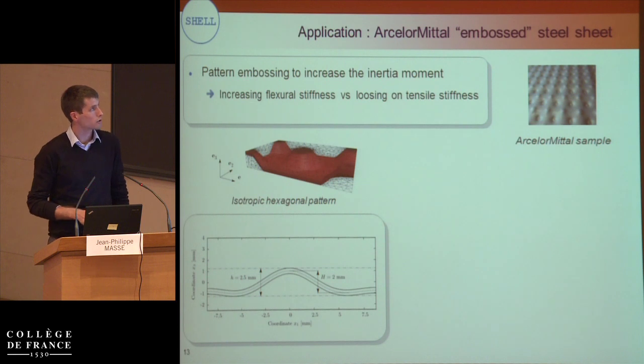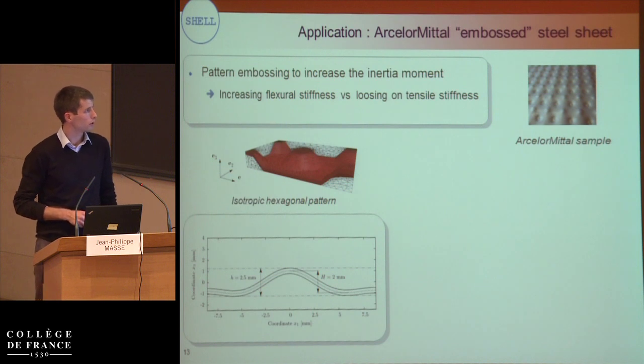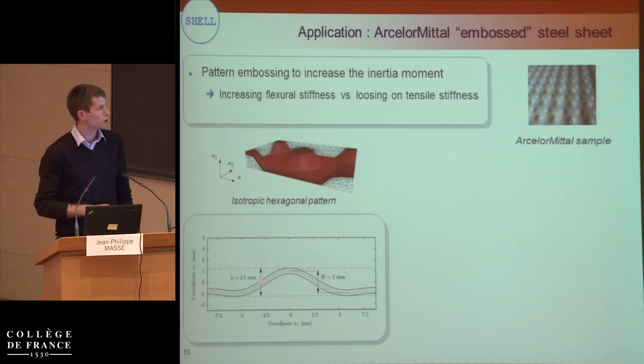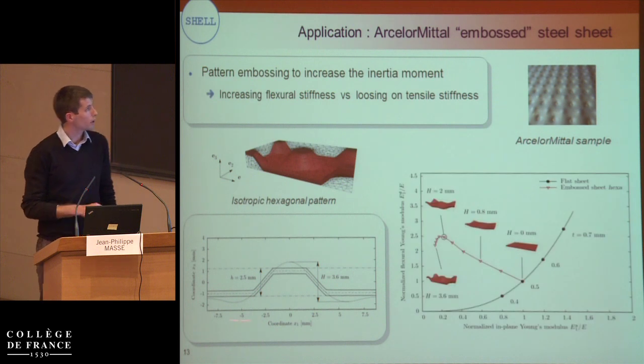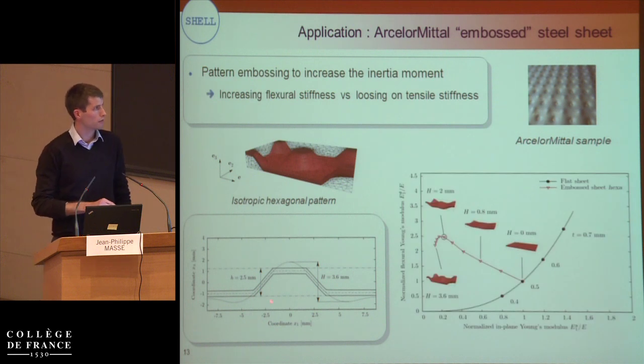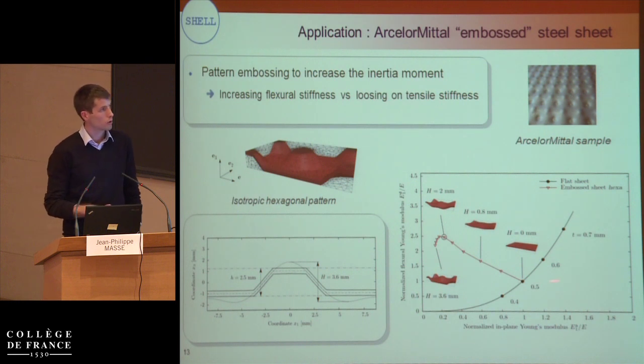We compute on the unit cell, so we mesh the whole unit cell and just define where we have matter of the sheet, and then we change some parameters, and so we are able, with a given maximum height of the corrugated shell, to compute for a given thickness of the sheet.